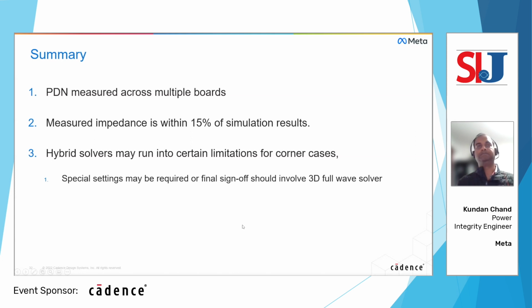So one of the recommendations we got from this was, in the initial sign-off phase, definitely we can use the hybrid solvers for an initial, quick check of how the PDNs are designed compared to spec. But for a final sign-off, just before your board or your product is taping out, ensure that we are using a 3D full wave solver to cross-check our results.